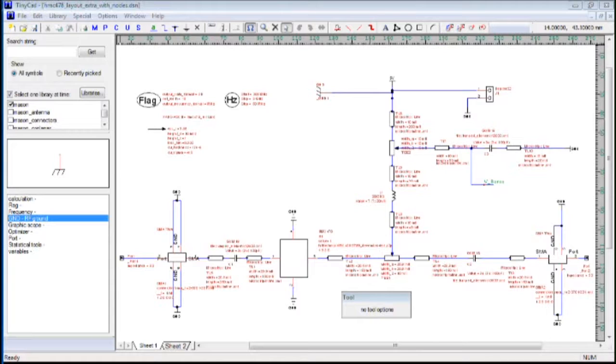Our 5 volt net is associated down to the second sheet where we had this microcontroller. We have the vSense net linked between where we're trying to sample the voltage and where we're trying to capture the sense of the voltage in the microcontroller.